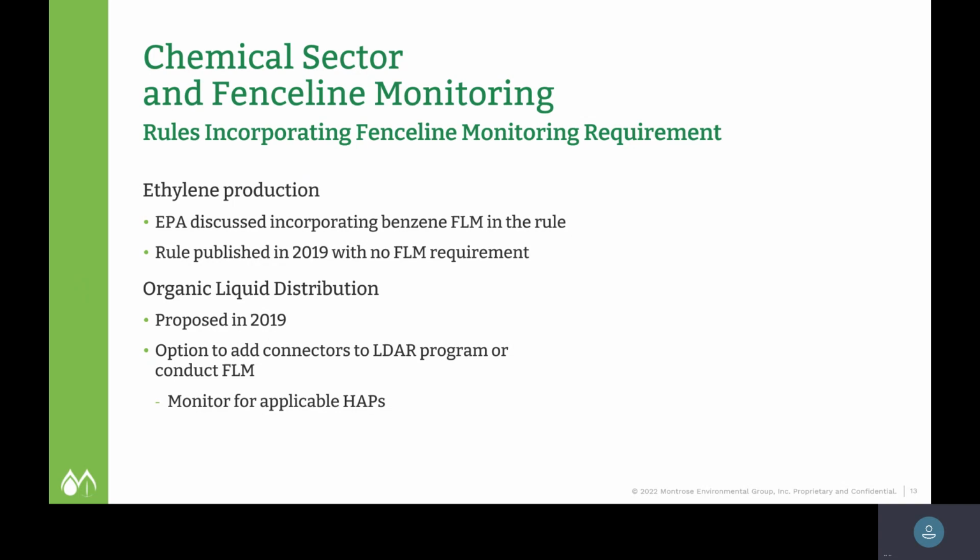So then skip over to organic liquid distribution, OLD. This rule was proposed in 2019. It provided this as an option, it wasn't a requirement, but the option was either to add connectors to these facilities' LDAR programs, or to conduct an ongoing fenceline monitoring program. The kicker here is OLD isn't for benzene necessarily, right? You've got who knows what, right? So does the method support it? Well, it might, but what would you do if it didn't?